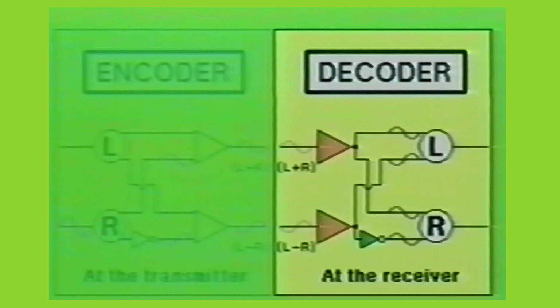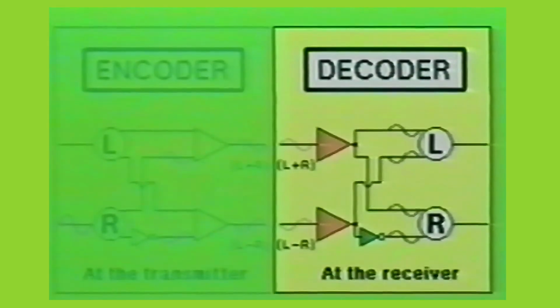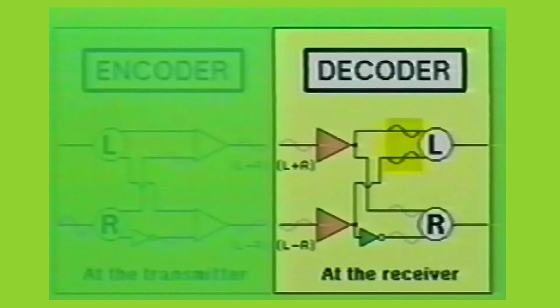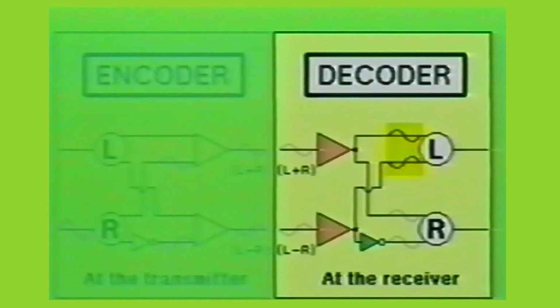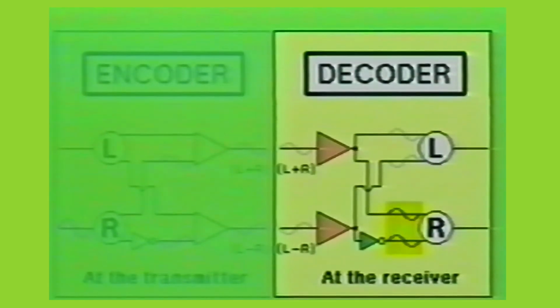The waveforms at the left channel are exactly the same but opposite in phase. Thus they cancel each other out and reproduce no output in the left soundtrack. However, the waveforms at the right soundtrack reinforce each other to reproduce the same right signal as was first seen by both left and right soundtracks of the matrix encoder.